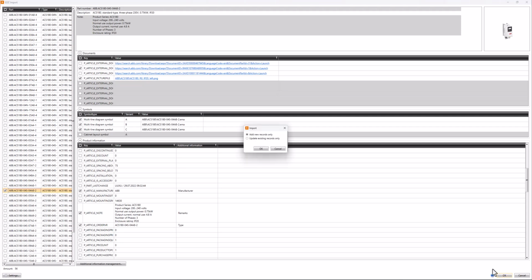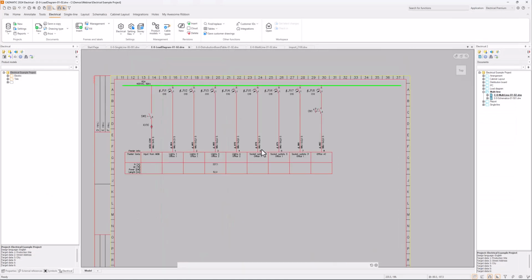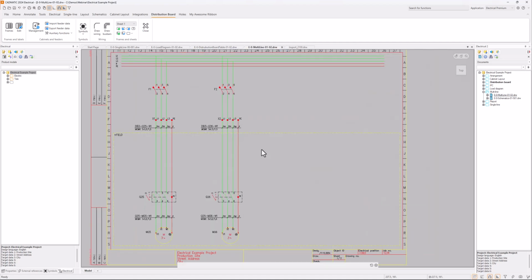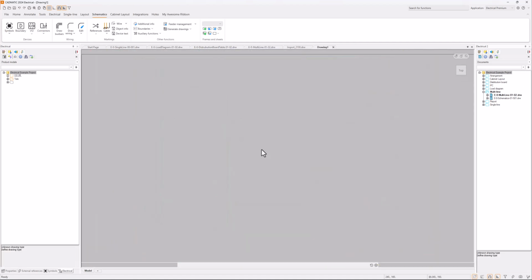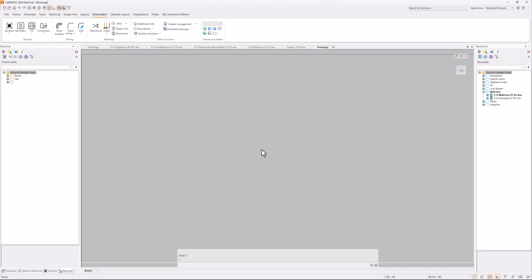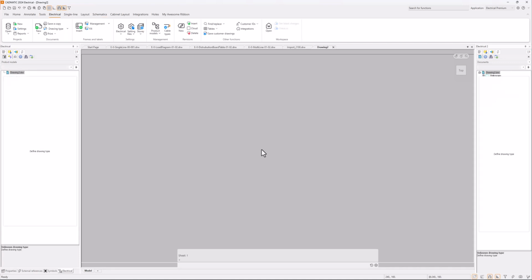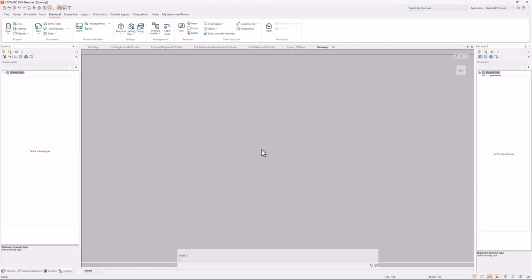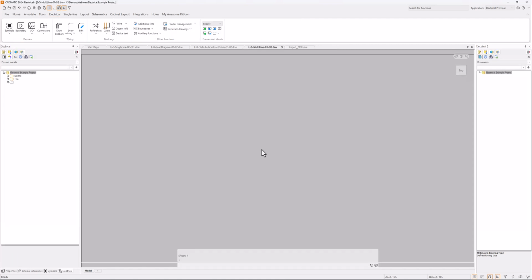Select OK, and then add the new records only. There's also a possibility that you want to update things, so you can update your ePlan macros as many times as you want. Maybe you have some new features coming, there may be new symbols. So if you download this macro one time, create it as a product model, and you are missing one symbol or some other information regarding that part, you can actually update the information from the EDZ file, so it will follow the same code.